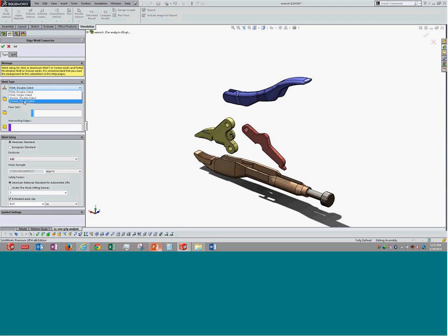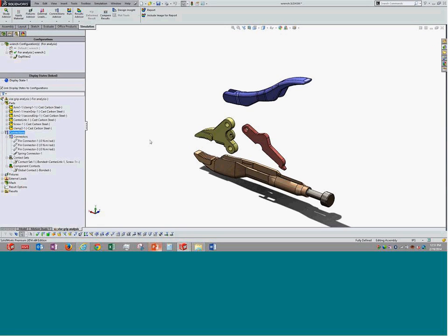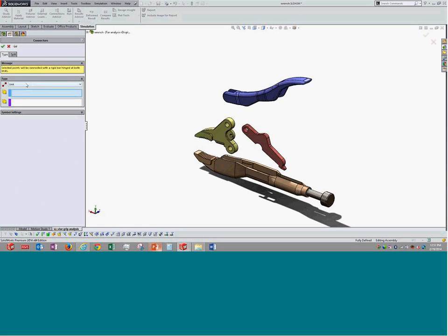And on doing analysis, again, we can understand the edge-related details in the sense of whether the given thickness is enough, and what would be the required thickness across the length. All those details can be understood. I think that is links and connections. These are more towards applying relative motion between two parts. So it has a bonded contact as well, but does not have any rotational degree of freedom.